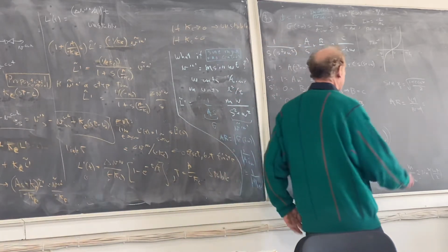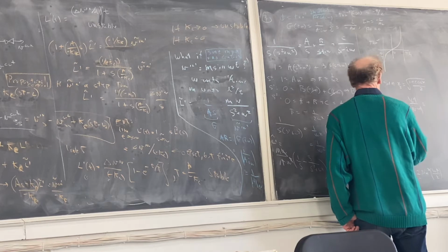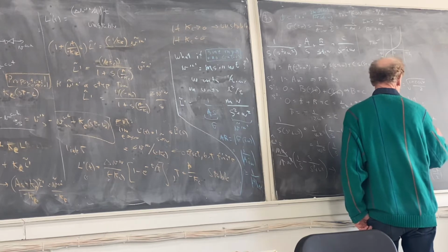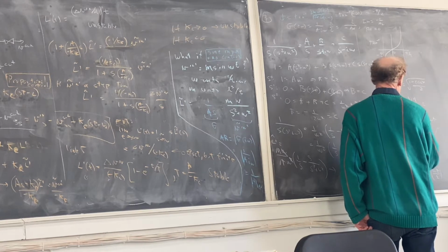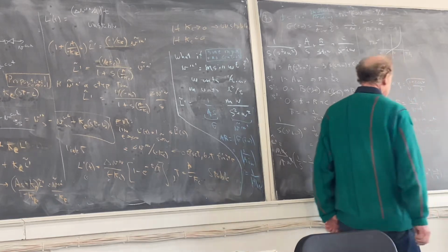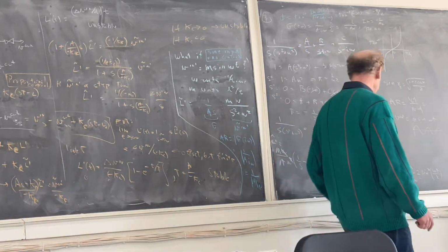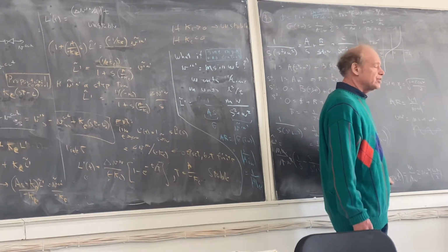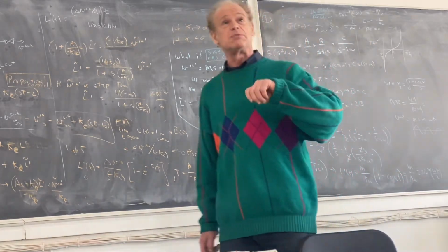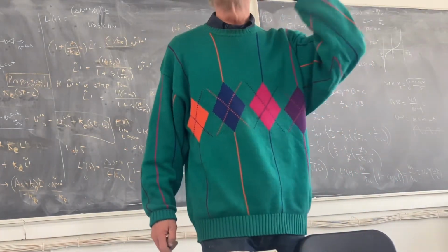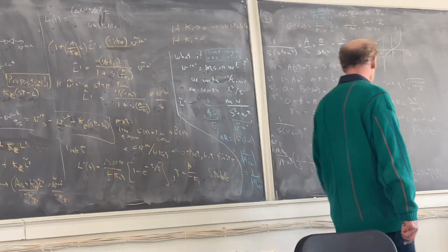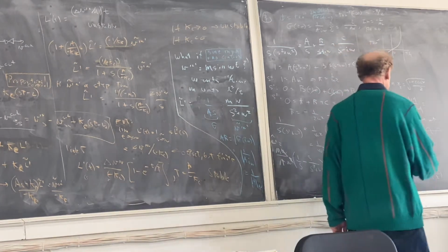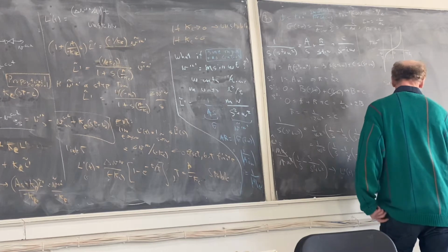And let's just notice that the input v in prime is m sine omega t. So the sine starts here. And let's notice the output. The output is 1 minus cosine. So the sine of 0 is 0. The cosine, what's the cosine of 0? How about some audience participation? What's the cosine of 0? 1. The cosine of 0 is 1. So 1 minus the cosine of 0 is just 0. So let's look at the output. I start out at 0.